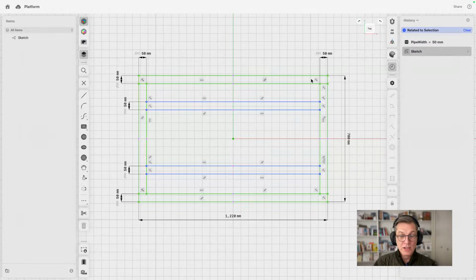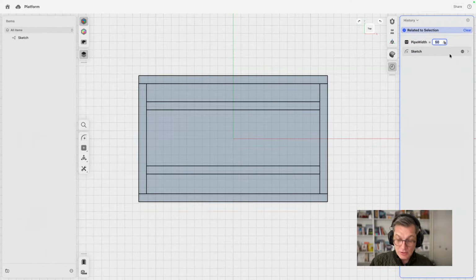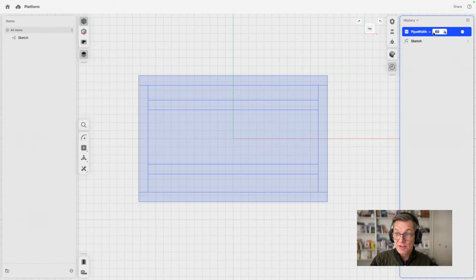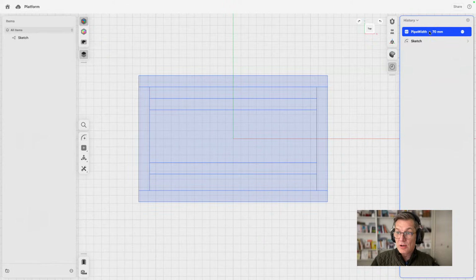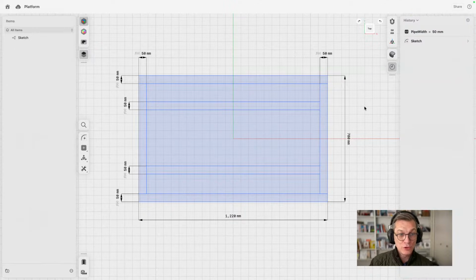Now, while you sketch or 3D model, you can create it, or you just do this at the beginning. So the nice thing is, you see that all these dimensions have an fx. That means this dimension gets the value from a variable. And now if I change this, for example, to 60, you see how everything updates. So I only adjust this variable one time, and then all these parts update automatically. So you can assume that's really a huge time saver.